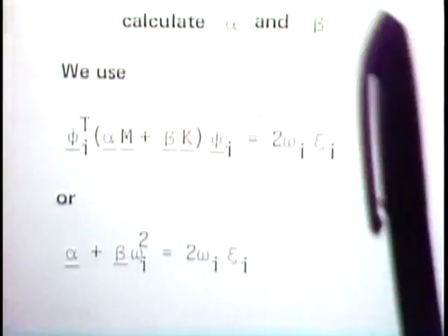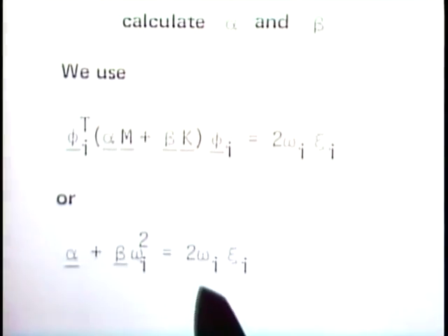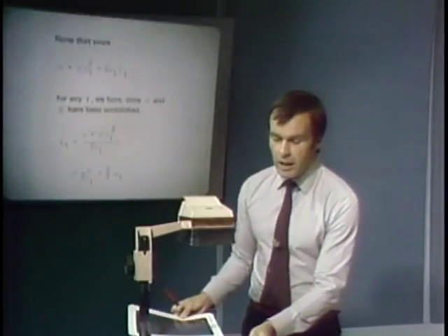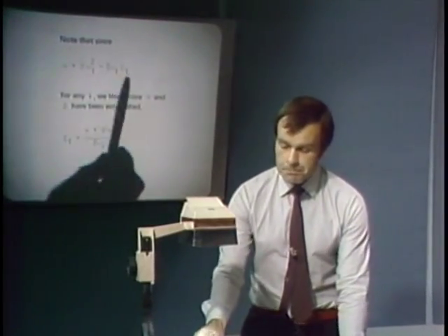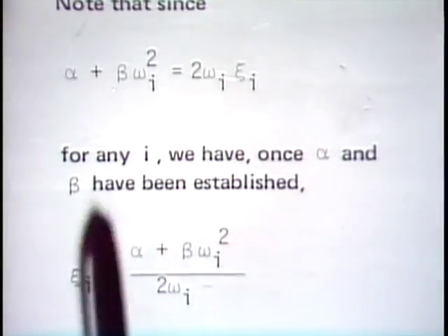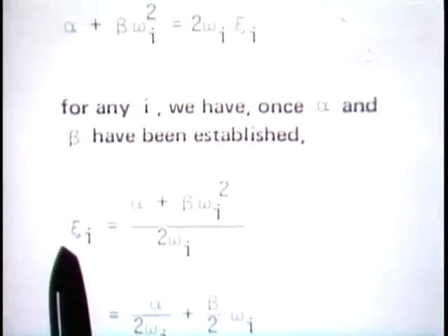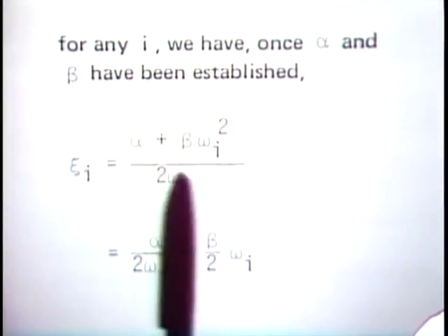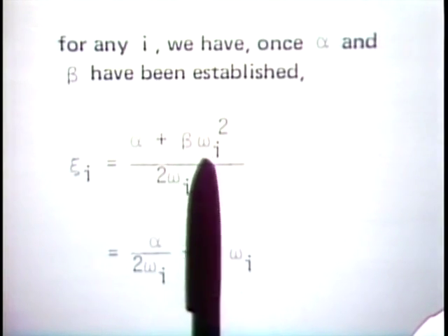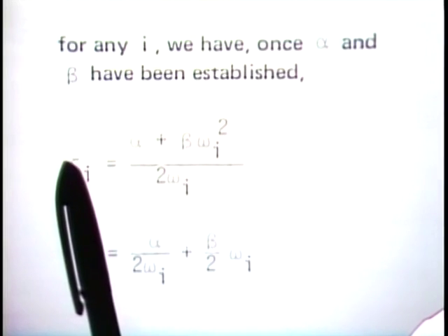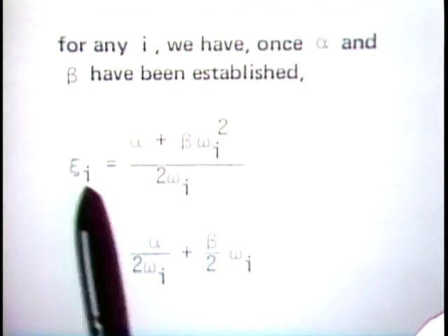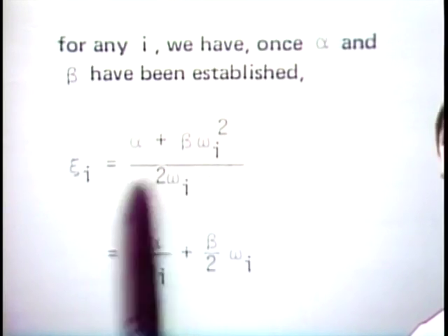See, you're now using this equation because this equation must be applicable not just for psi1 and psi2, but for all psi values. Well, then using this equation, we can solve for the psi values, and of course psi1 and psi2, substituting alpha and beta in here, and omega 1 and omega 2 would indeed be just 2% and 10%, 0.02 and 0.10. However, we can now use this equation to get the higher psi values.